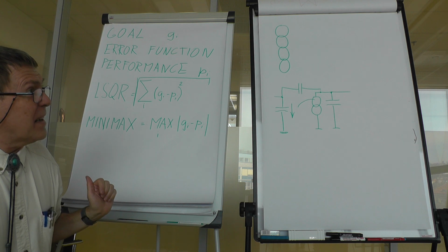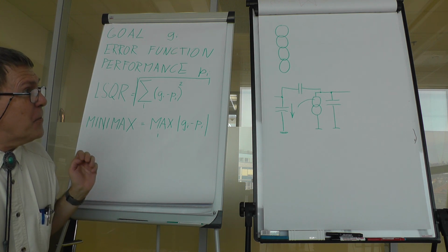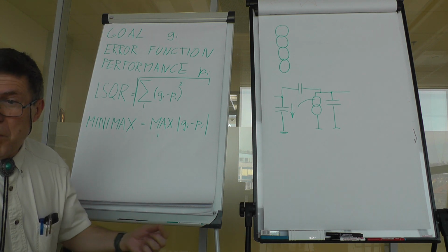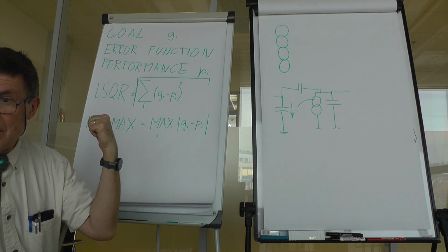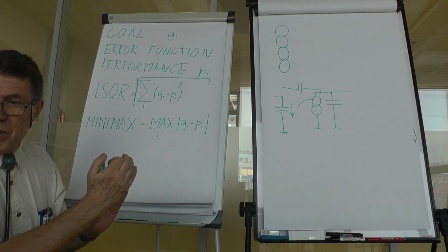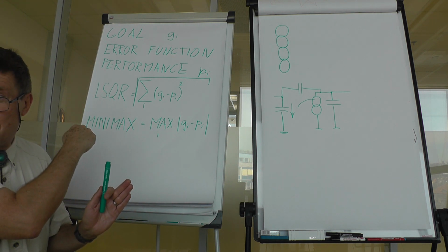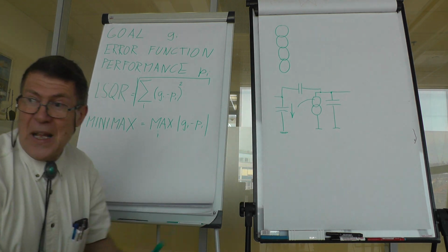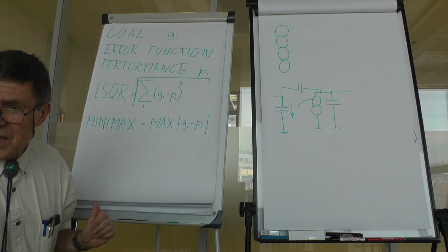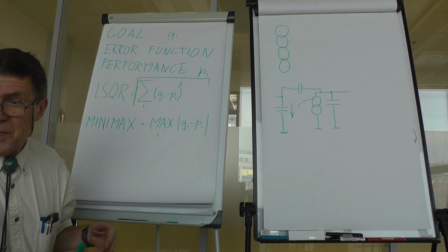Now, classically, this feedback is responsible for backward transmission through the transistor. So if you have the transistor, you get some transmission of the signal from the output to the input through this. And classically, it's very small at low frequencies, several orders of magnitude smaller.